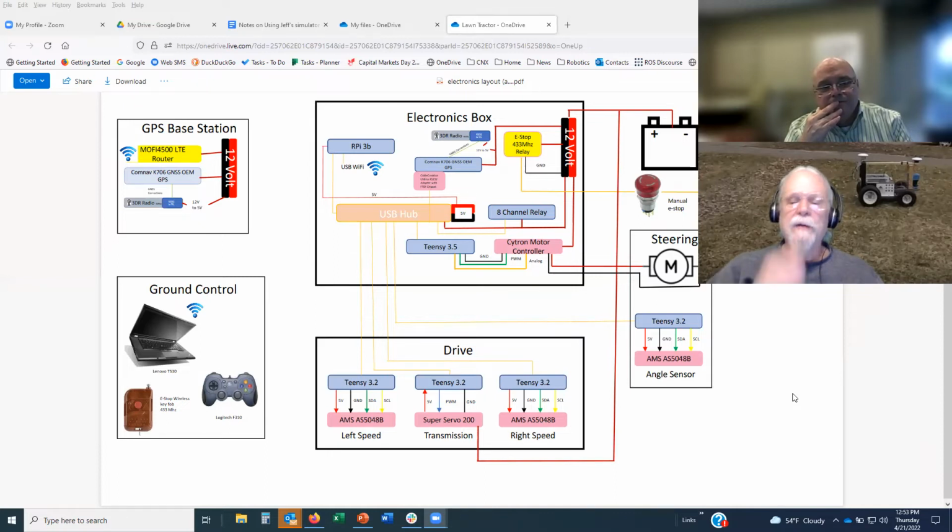So I was just talking about separating out communication and power, and this is more of what I would call a high level block diagram. You show a battery with just a single line coming over to something called 12 volt. I don't know if that is a bus bar or a fuse block or whatever that is, which doesn't really matter, but the point is you're not showing the ground returns. So this is not an actual wiring diagram of what's hooked up.